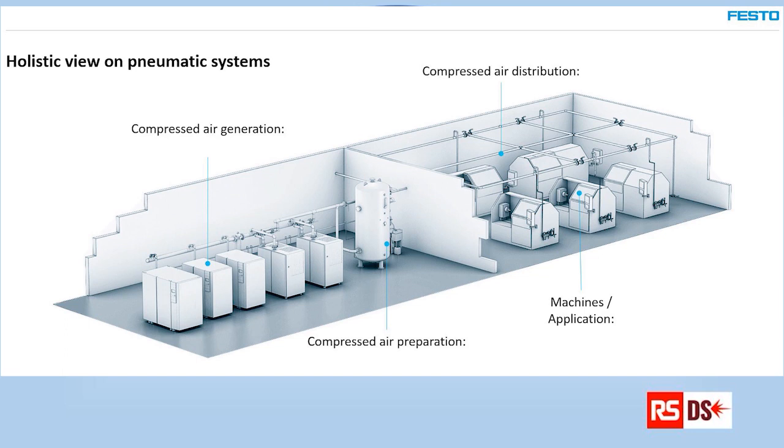And if one component is changed to possibly save energy, this can have negative consequences and perhaps even cause higher energy consumption at another component. Therefore, the compressed air system should be considered as a whole system. An example: the compressor supplier makes an analysis and selects a new compressor according to this calculation. In the meantime, however, leakages are searched for in the production and will also be repaired. Thus the consumption is reduced and the compressor is much too large, and then it's not operating efficiently.